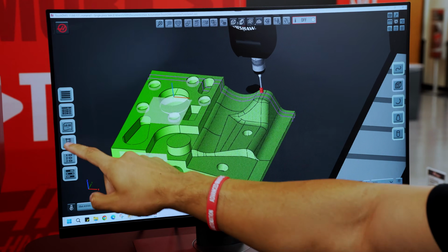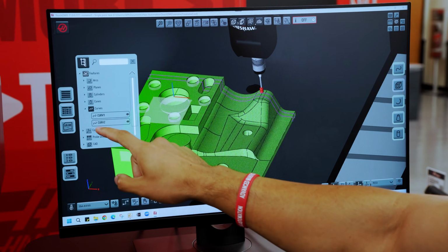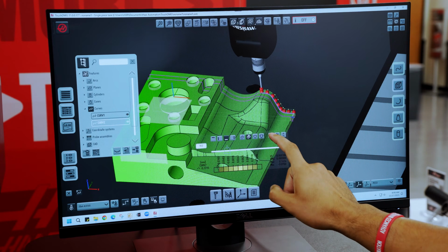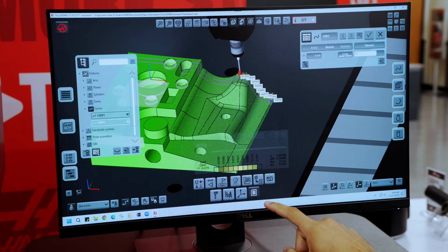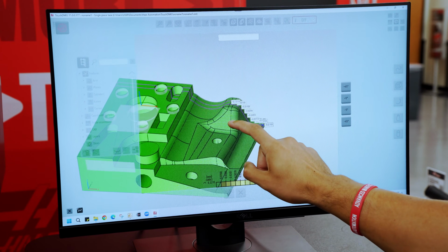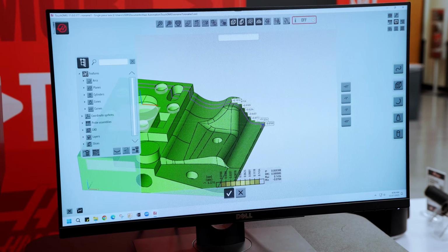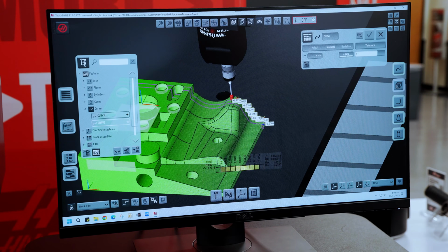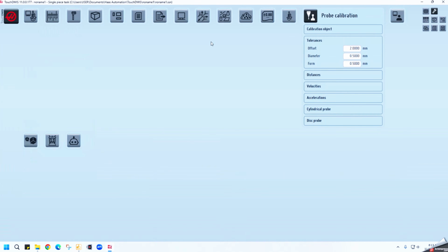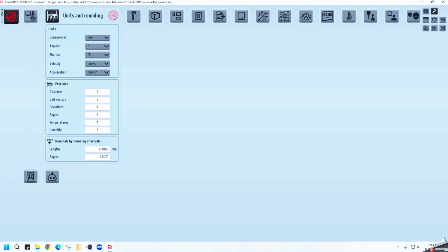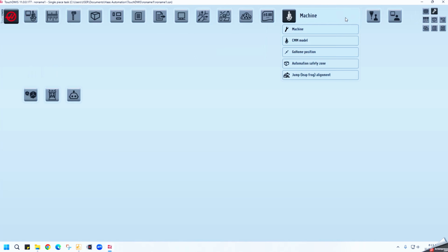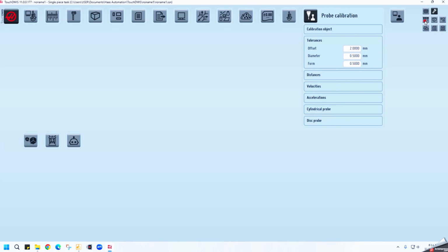To take a screenshot, I'll open the Hierarchy window, select Features, expand the Curves dropdown, and select the curve I just measured. Then I'll click on the report icon, select the camera icon, frame the model, and click the check mark to take the screenshot. The screenshot is automatically sent to the tabulated reporting window. The tabulated reporting window can be found in the upper right corner along with the TouchDMIS's System Settings, Probe Management, and Workspace features.